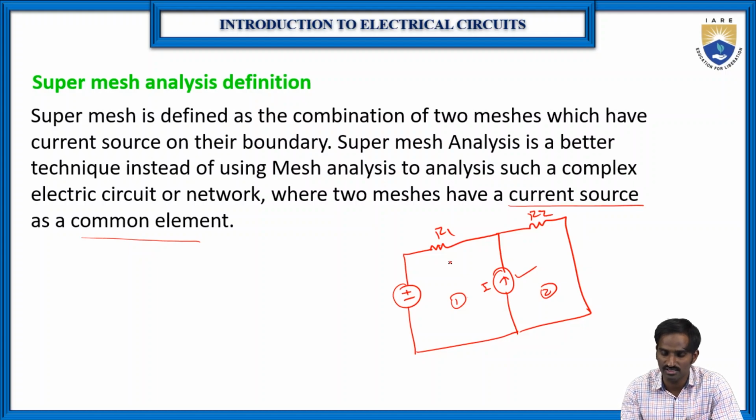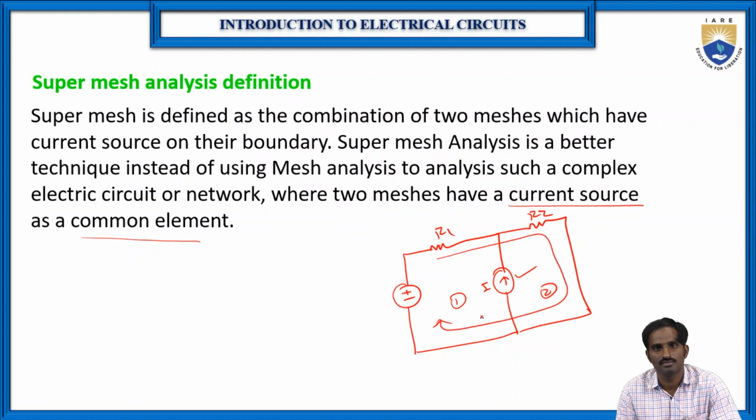In the super mesh analysis we take this whole as one circuit. By that way we can solve this problem and find the voltage across R1 and the voltage across R2. This is about the super mesh analysis.